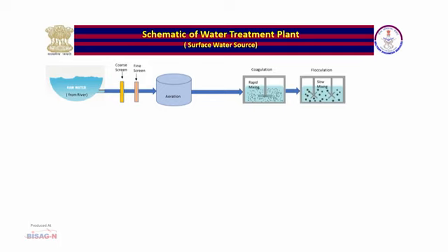In simple words, the combination of rapid intense mixing and stirring, that is slow mixing, that produces aggregation of particles is designated by a single term, flocculation. The common coagulants used in water works practices are salts of aluminium such as filter alum, sodium aluminate and liquid alum, and iron salts such as ferrous sulfate, ferric chloride and chlorinated copperas. Selection of aluminum or iron coagulants is largely decided by cost and its easy availability. The chemical coagulant is normally introduced at some point of high turbulence in water.